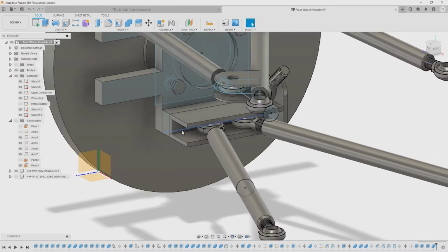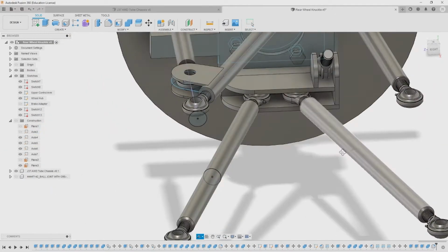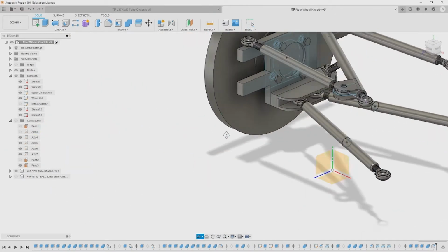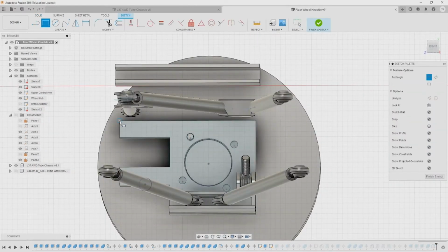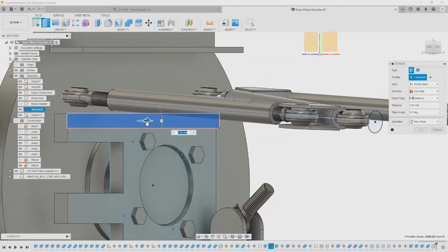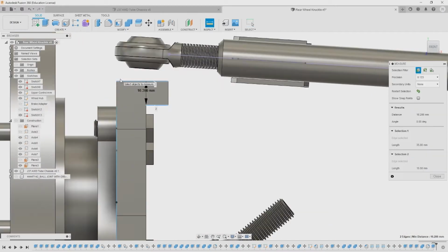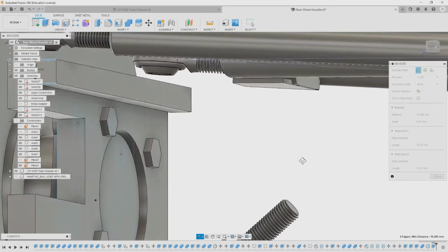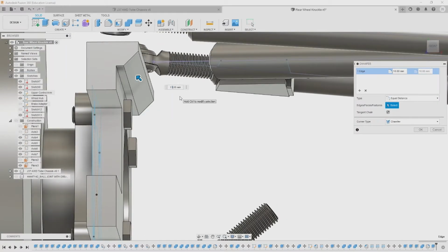Moving on, I'm going to begin working on the upper part of this hub, and I'm trying to change this up a little bit. What I'd like to do is actually drill and thread the holes that those rod ends are going to connect to right there at the top. So you can see here I'm going to extend this material out a little bit and then just taper it a little bit to make it easier to get to those lower bolts. There should be about 3/4 of an inch of bite for the hardware. I think that's going to be more than suitable.